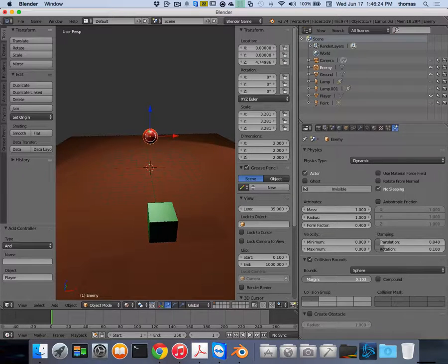So if I go back, it's an important thing to understand how physics visualization works. If I increase my margin, if I go way higher, like up to 1, and go P for play, just notice my margin didn't really change anything. If I change my margin to way down low, like 0.00000 something, and go P for play, still, it's pretty large, this bounding box. So where is it housed? How come it's so huge?